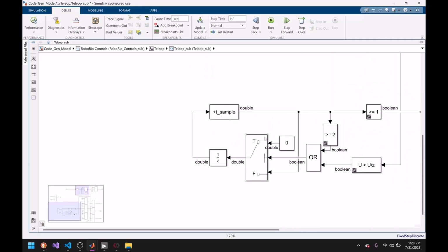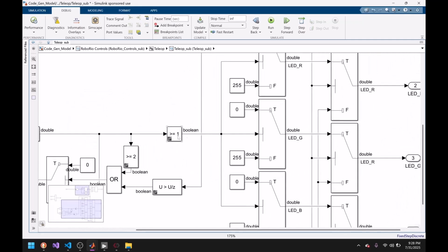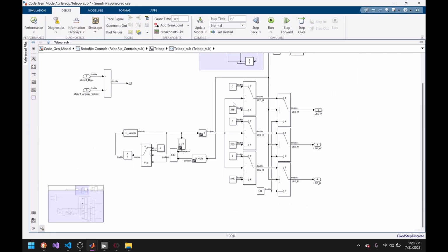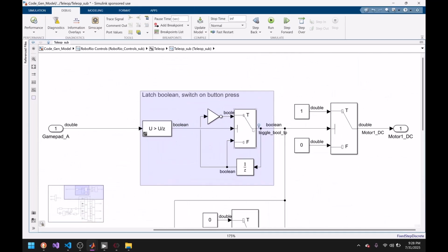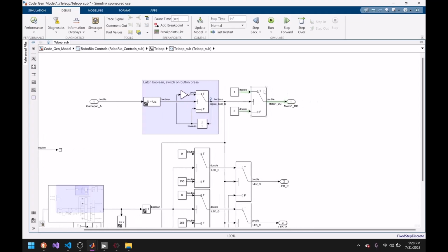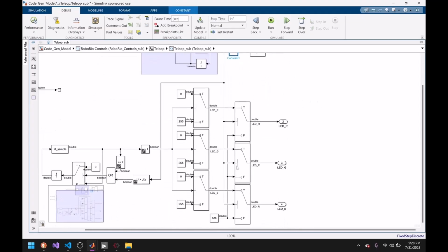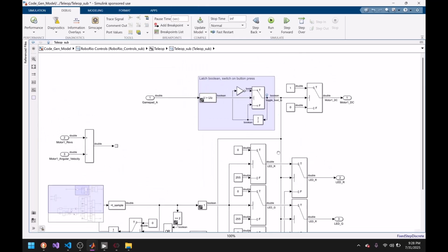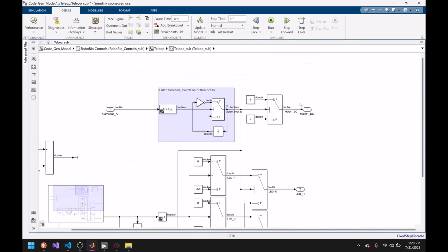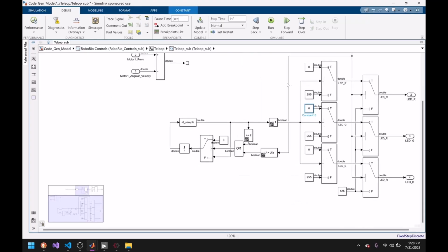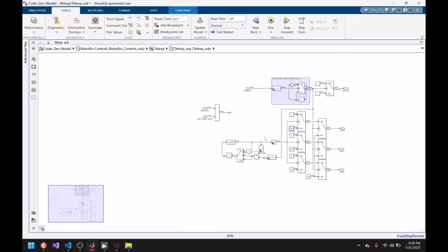And since 0 is what it sets it to, and 0 is less than 1, it's going to set to 255. So we have basically two cases here after the switch statement. We can have 0 here and 125 for RGB, or we can have 1 for the motor DC and loop between 0 and 255, starting on 255 every second. That's what this is going to do.